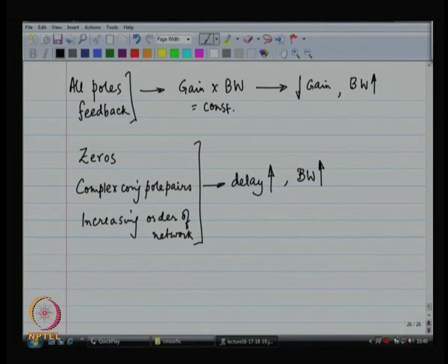All of the earlier techniques by placing an inductor, T coil, etc., were basically to emphasize this fact that you allow the response to be delayed, but it is going to be sharper. So, instead of getting a slow response starting now, I will get a fast sharp response starting a little later. This is basically the idea.